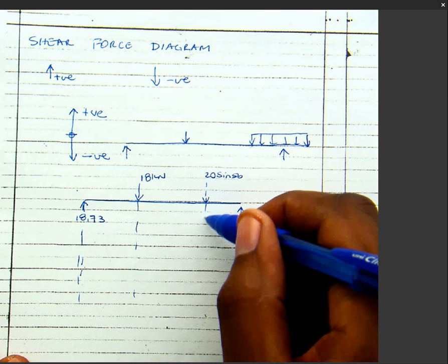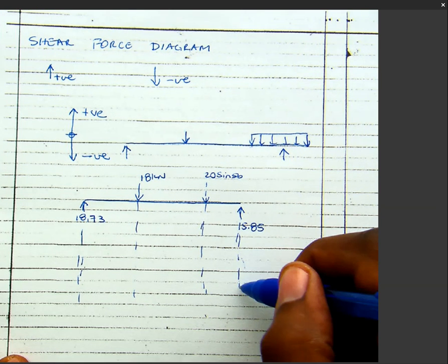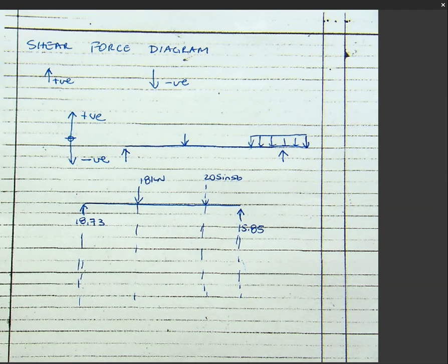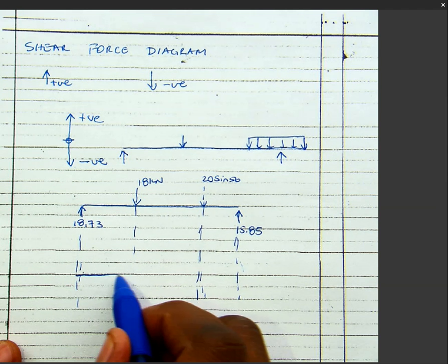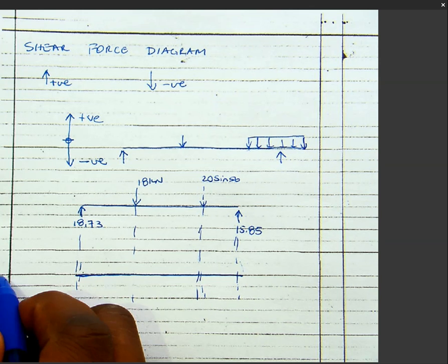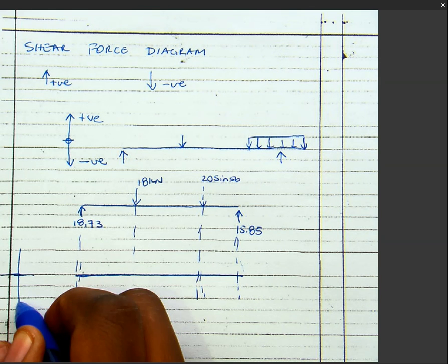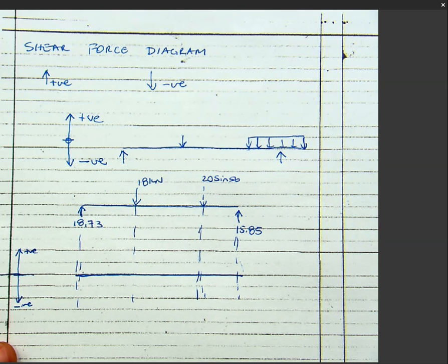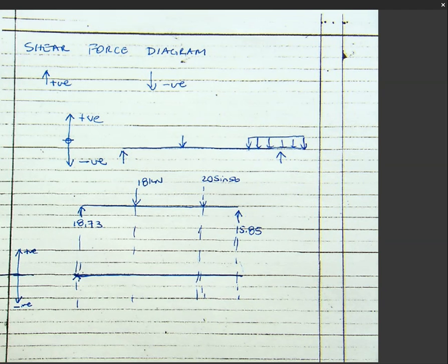Okay, I'm just explaining the shear force diagram for now, guys. Then when I'm done explaining my shear force diagram, I am going to explain how you approach a bending moment diagram. Okay, then there's my beam. Remember, positive, negative. Whatever we do, guys, we always start at 0. The first point that you plot there is 0.